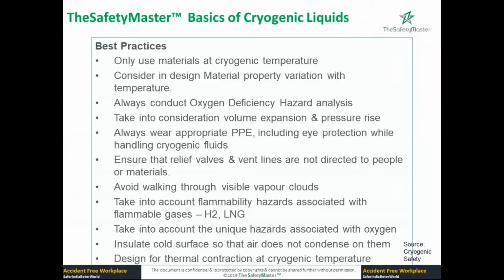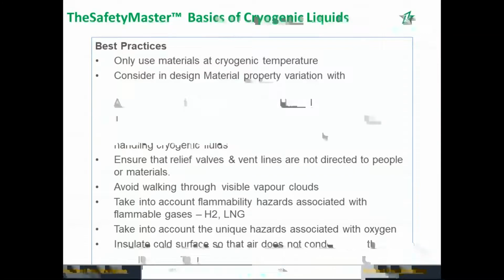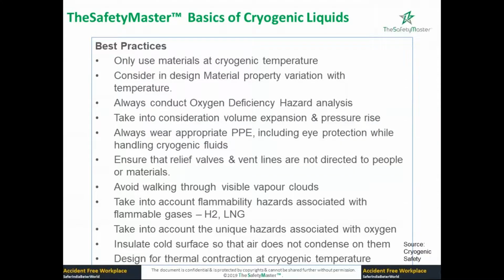And then relief valves and vent valves should not be directed towards people or material. You should take care, because when we have the vent valve in the design, it is taken care of. But if you happen to do some maintenance, or change the relief valve or vent line position, it should not be directed towards people or other material. Because if it's directed at another material, when this cold vents out of the safety valve, it will hit that material, and if the material is brittle, it will break. These are the issues here.